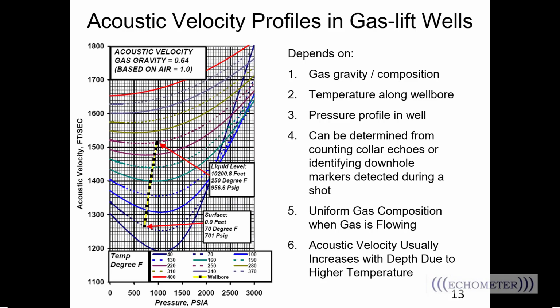And we're looking for the valve that's closest to the fluid, above the fluid level. So typically once we see the fluid level, we're not going to see past that. So you're going to find the closest mandrel or valve above the fluid level. So if that wasn't specifically your question, Joshua, please let me know.